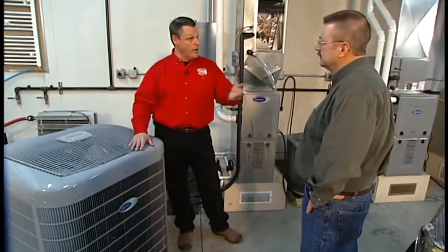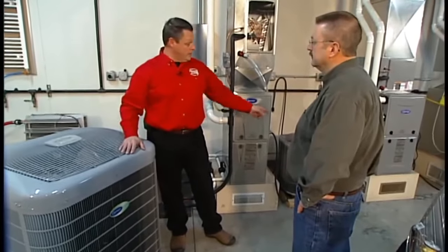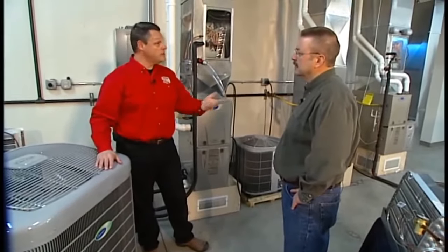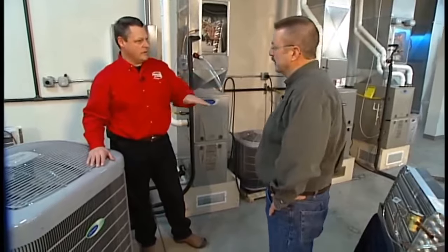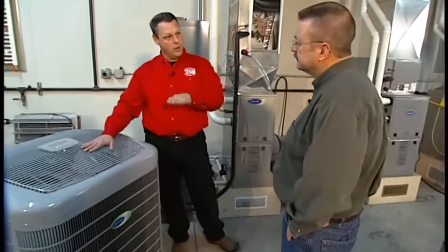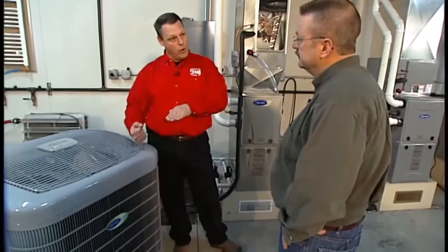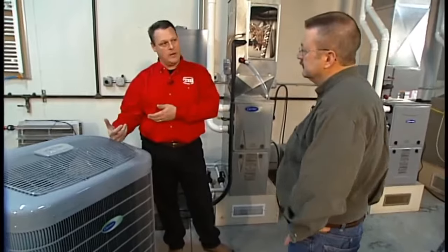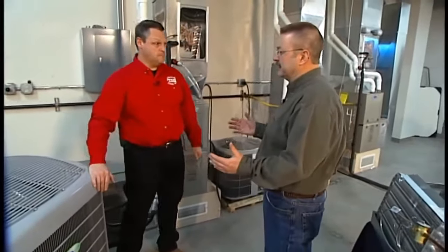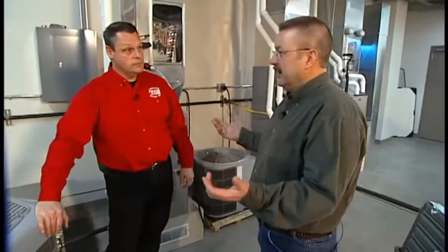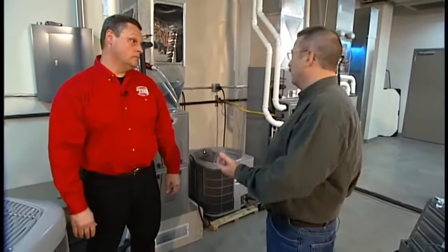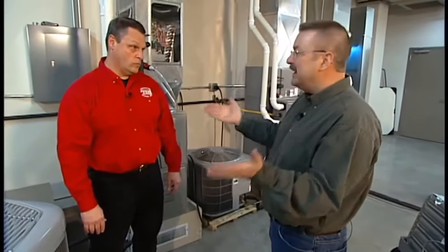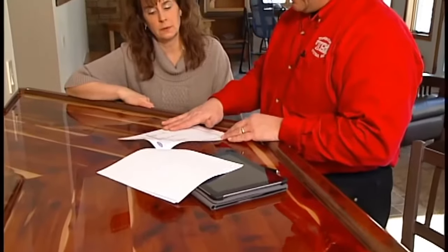The importance of that is we go back to that 80-degree day comparison you mentioned. This unit would run for a much shorter period of time, not being able to extract as much humidity out of the air, which is important on that high humidity, relatively mild day. Sure. This unit can run at a lower speed, lower capacity, wringing more moisture out of that indoor air, which is going to make us more comfortable, and it's going to get that humidity out of the house, which is really what we desire. So those are some great factors to consider from a consumer standpoint. Don't just necessarily run out and get the higher efficiency or the lower one based on price. Think about your living environment, your situation, back to that needs analysis you've created with your contractor.